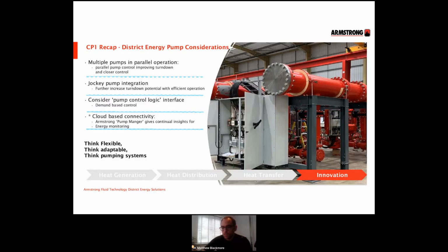So what does the design guide prompt us to do for the hydraulic pump system? It asks us to consider multiple pumps in parallel, so selecting a larger number of pumps, so 3 at 50% duty, 4 at 33%. We still maintain the redundancy, but it does open the door to more efficient operation over the whole profile. It asks us to consider the addition of low flow pumps.